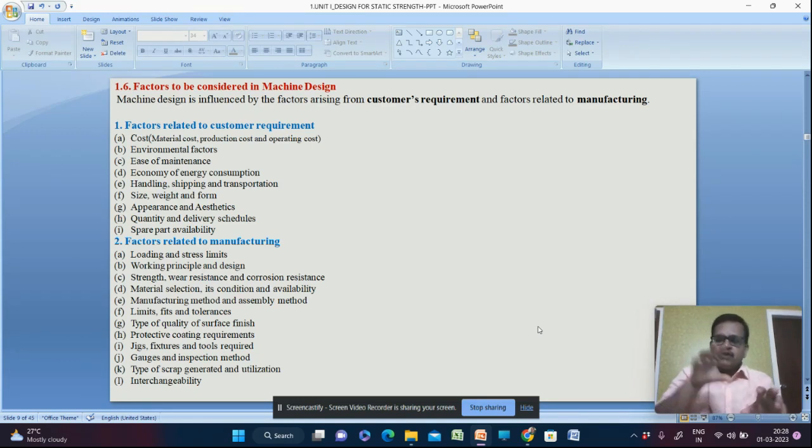If the shaft comes with minimum size and the hole also comes with minimum size, the shaft cannot enter the hole. And if the shaft comes with bigger size and the hole with minimum size, definitely it cannot enter.